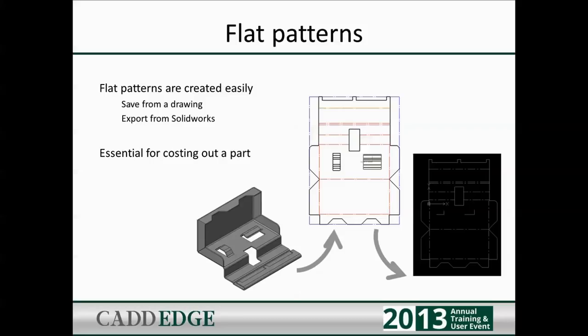So talk about flat patterns real quick. So flat patterns, if you're costing out a part, they're typically valuable. I'll say that, only because when we get to the SolidWorks side of things, you'll see how it varies with it. But flat patterns, we can see what our flats look like, where our bend lines are, center points on our form tools, etc. So we can save them right from a drawing, or we can export them directly from SolidWorks.